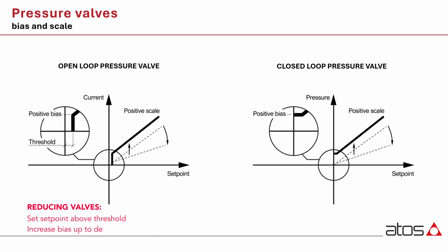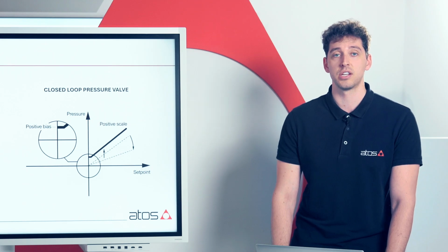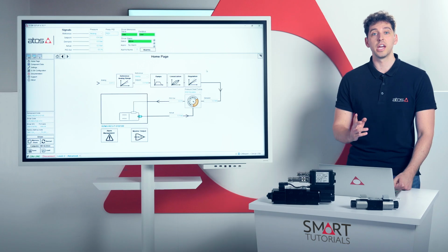For reducing valves instead, set the set point slightly above the threshold, and then set the bias to reach your desired minimum pressure. The procedure for closed-loop valves is the same without considering the threshold, which is not necessary for valves with integrated pressure transducer. Scale for pressure valves limits the maximum pressure.